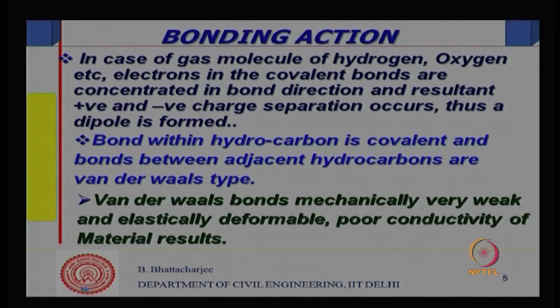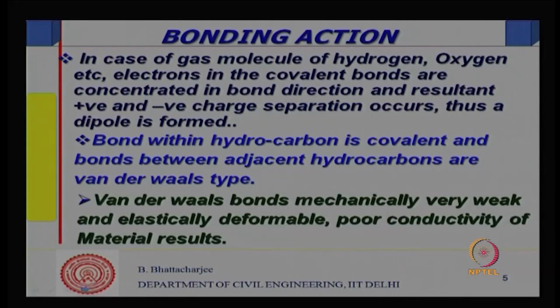So, CSH gel has this sort of bond, which is not a strong chemical bond, but a van der Waals kind of bond, and gel to gel separation requires breaking those van der Waals bonds, right. Many other materials do not have any bond at all. For example, sand particles: between sand particles there are no forces of attraction holding them together, or stones, with large surface area, small surface area compared per unit mass or per unit volume, the forces do not act,